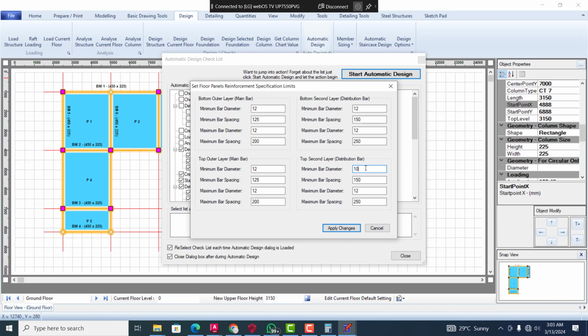Maybe Oga will share more light on it. You provide a reinforcement at the top, so that's what they call the top distribution bar. Maybe sir, maybe you can share more light. Yeah, that's correct. I think most of them have been to sites, so that's basically what that is. Me personally, I normally use 300 myself. So you can set it to minimum 300, maximum 300. Let it not go more than or less than 300. So this one too, you can set it however you want.